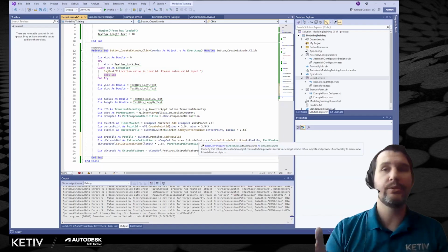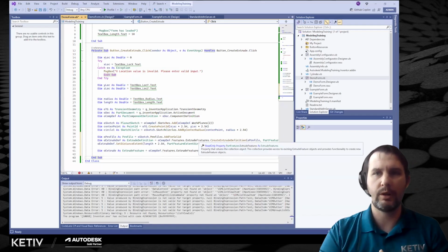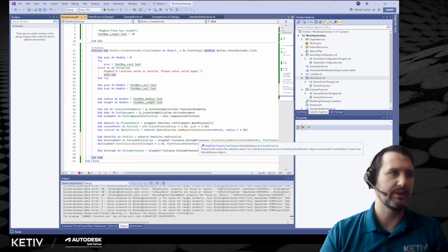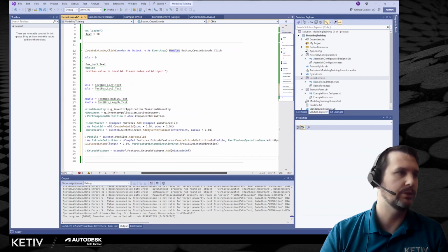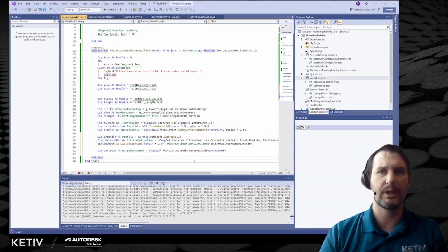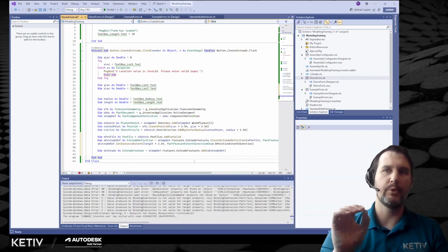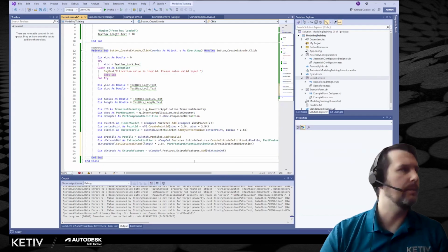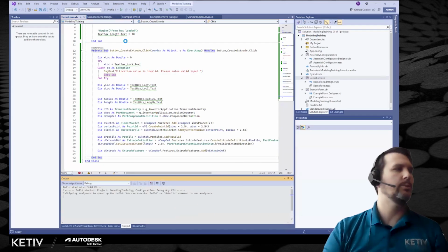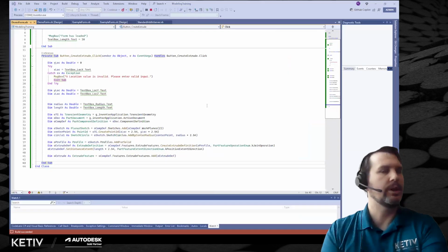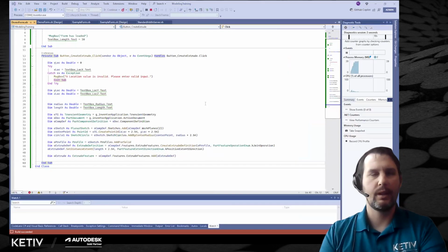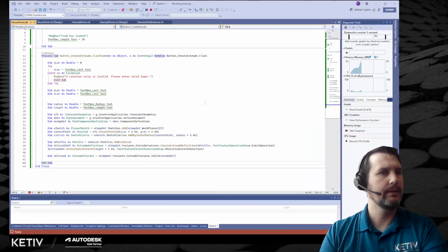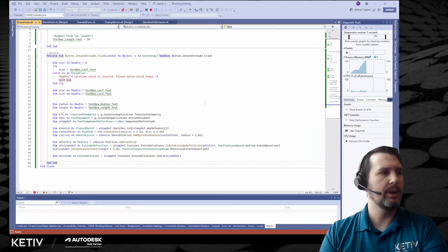Now, you can do the same type of thing if you want to do a revolve, or if you wanted to make this a cut, you'd change this from a join to a cut, and you can kind of get those complex shapes that you're after, doing piece by piece. But for now, let's go see how it looks. We'll run Inventor and make ourselves an extrude.